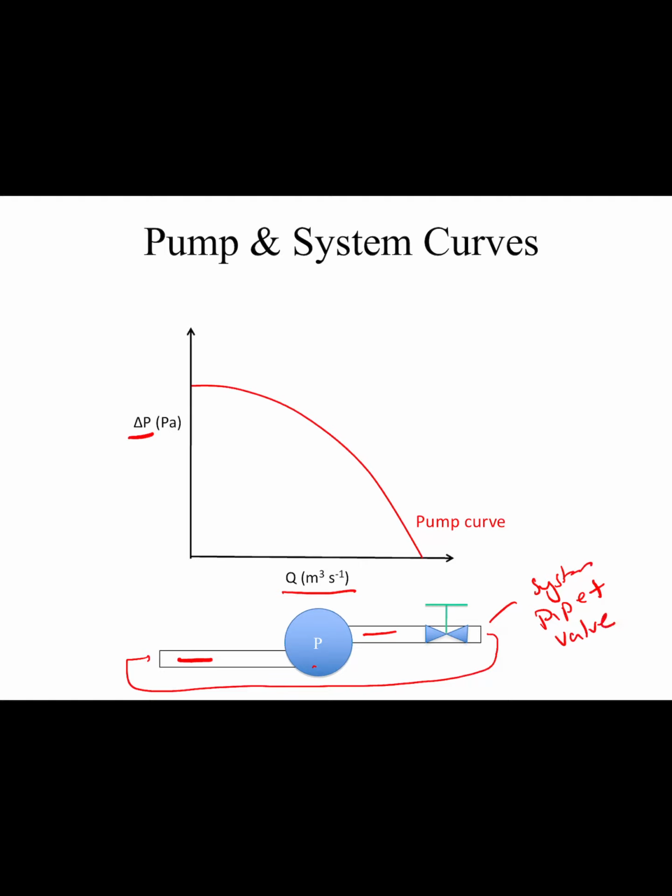If I wanted to calculate the head loss associated with that, the total head loss would be equal to the major head loss for the whole length of the pipe plus the minor head loss due to the valve. If we have pipe parts in series, we can sum the different head losses to get the total pipe pressure drop. But then we also have the pump. It's not a pressure drop; the pump increases the flow energy and raises the pressure, and it depends on the flow rate.